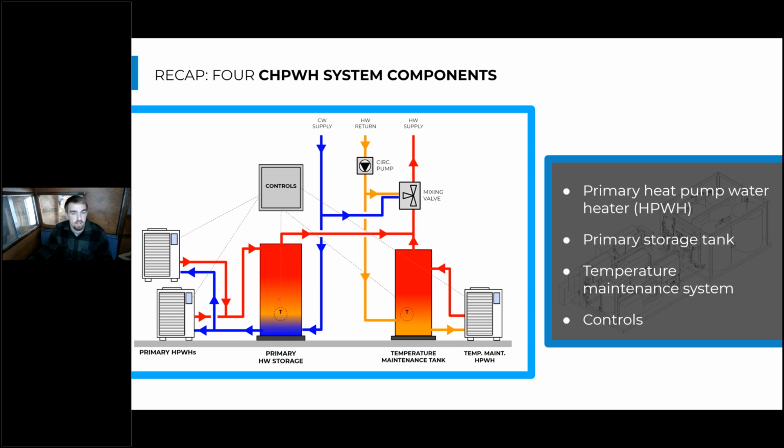Right, so with a combined temperature maintenance system, you have to be really careful to work closely with the manufacturer or their rep to make sure that their equipment can handle those higher entering water temperatures, as well as coordinate closely with the controls to make sure that those tighter tolerances of on and off set points can jive well with this higher entering water temperature to the bottom of the tank.